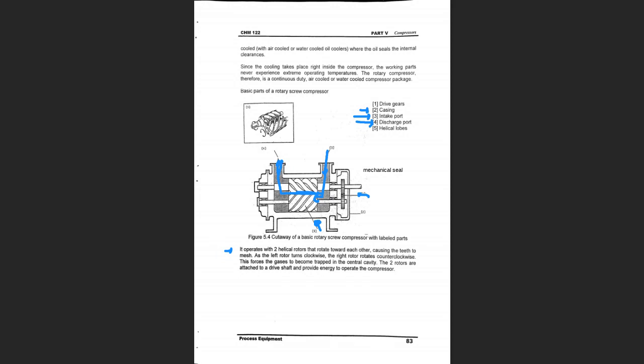You can almost use the same description of the rotary screw pump. Even if you get stuck or feel that the wording here is somewhat different, and you have an objective question to describe the operation of the screw compressor, you can write the one we have in the pump in chapter 1, because the principle is the same. We have two gears, one driving gear, one idle gear, two rotors or two screws rotating in opposite directions, and it is the exact same operation. Okay.